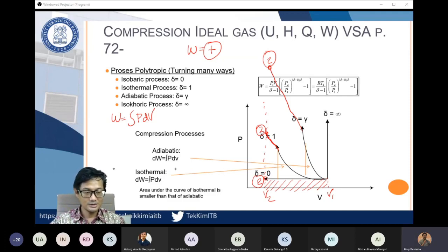Pak Sanggono will mention how you can read heat capacity as well as steam tables based on your knowledge of each condition: isobaric, isothermic, adiabatic, and isochoric. In fact, later on, we will revisit the steam table to understand the meaning of isenthalpy and isentropy. But that one is after we move to the second law of thermodynamics.